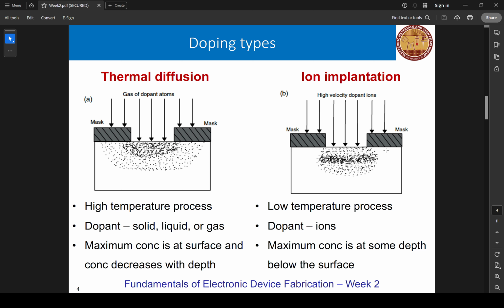Between devices there are much deeper oxide layers. Those are very complicated processes. So my point is, when we are doing our ion implantation, there is already a grown oxide layer on the surface. Our ion implants are first going through that oxide and then into the wafer.